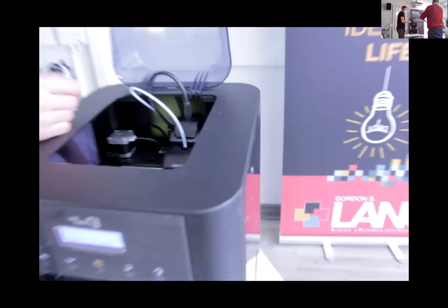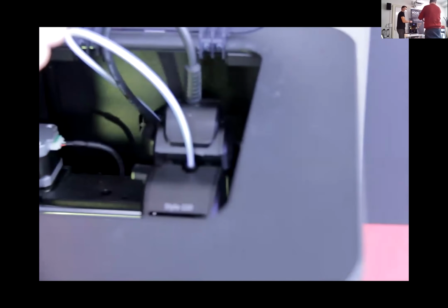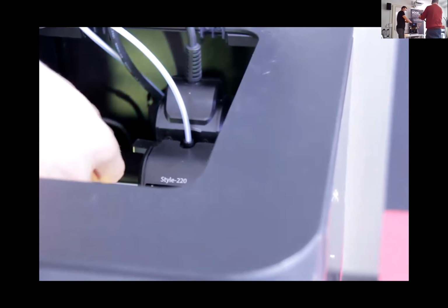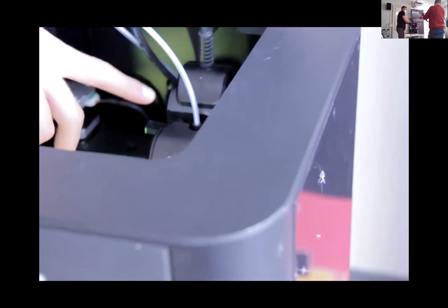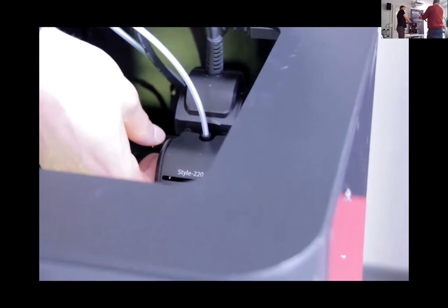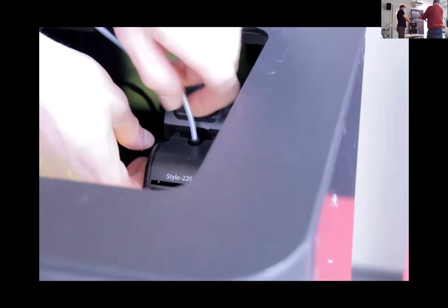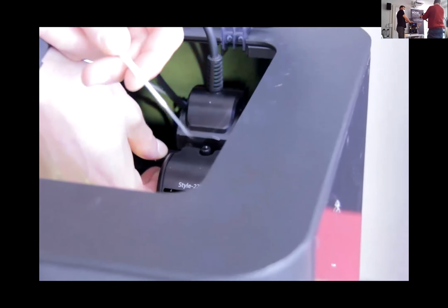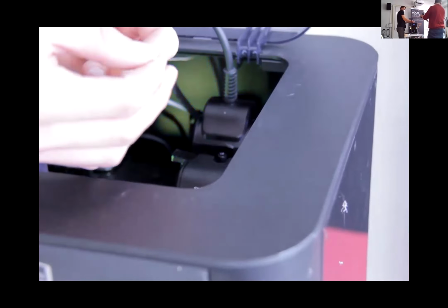So remember on the Ender, there is a filament holding clip that we pressed by the extruder motor when we were pushing new filament in. Well, the Cubicon has that too. There's a little clip in here. We're gonna push the clip down, pull out the Bowden tube and our filament. And there we go. There's the end of our filament.